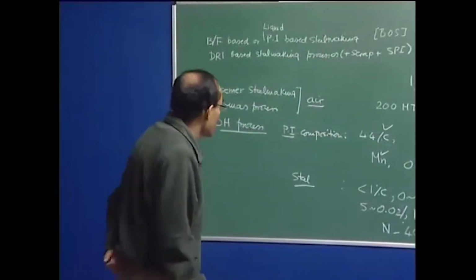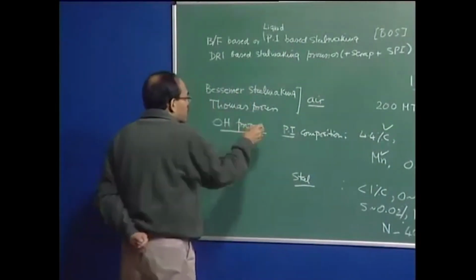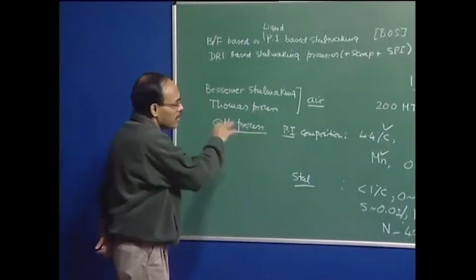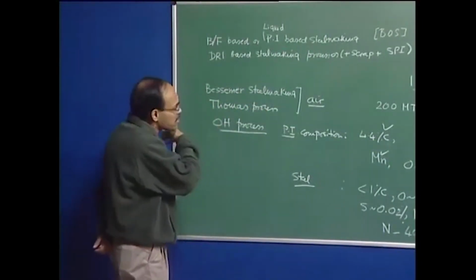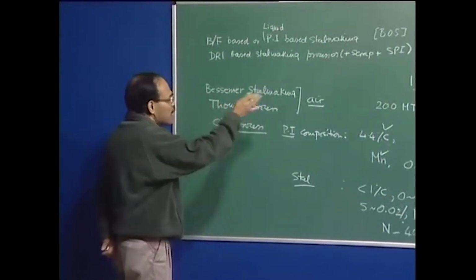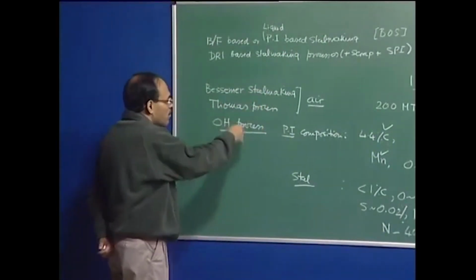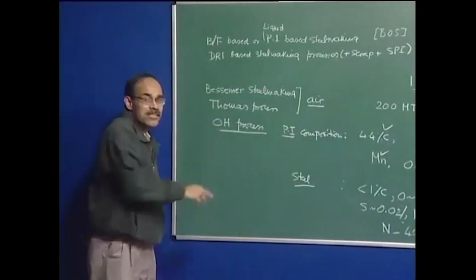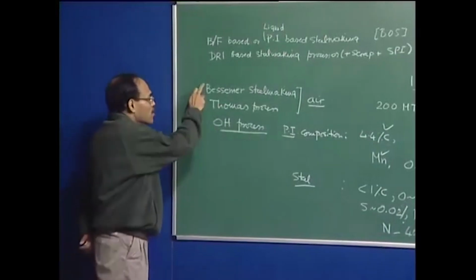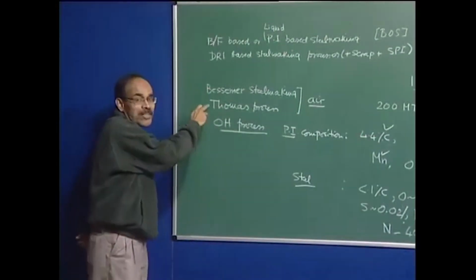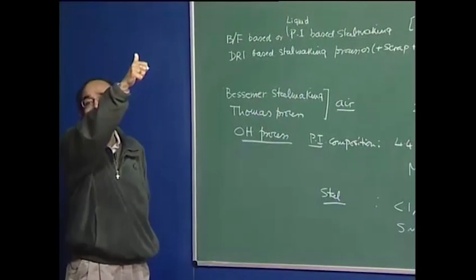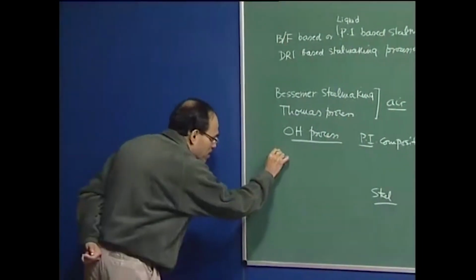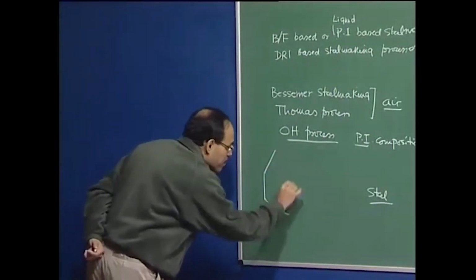So, coming back to the history of steel making. Air has problems. Acid steel making, which is the Bessemer steel making process, has basically been phased out. The basic Bessemer process has also been phased out now, and the open hearth process is not a pneumatic process. So, these are bottom blown converters. Through the bottom of the converter, which is nothing but a pear shaped vessel in which steel is made, air is blown.